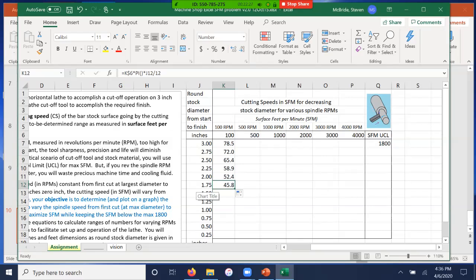Now, let's look at the J. Well, it so happens that I didn't move sideways, so the J was good at keeping that as a J. So that should work for that row. But now I copied those on down and just do a double check. It's always good to check. So it's K6 times pi times the diameter J18 divided by 12. Perfect.